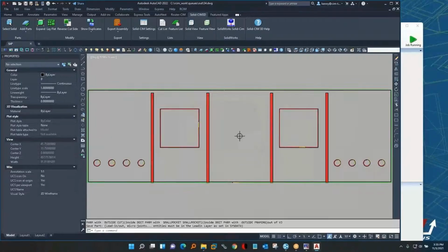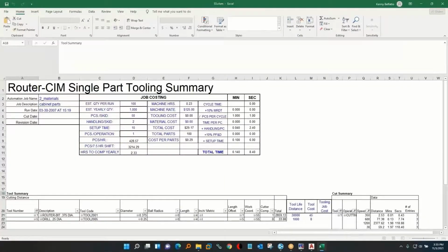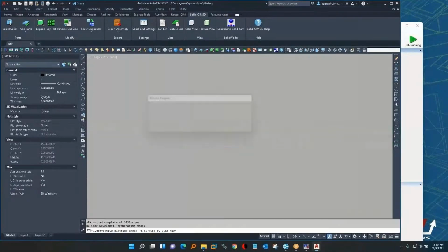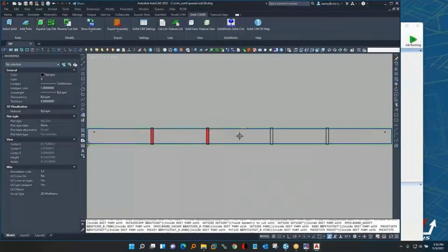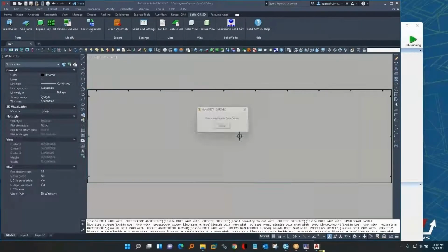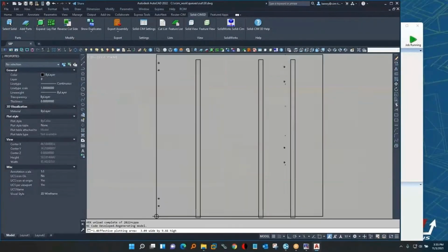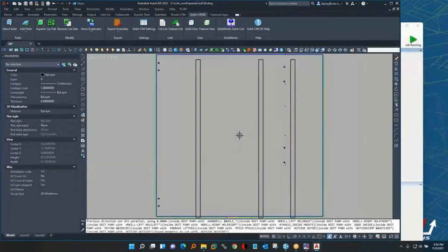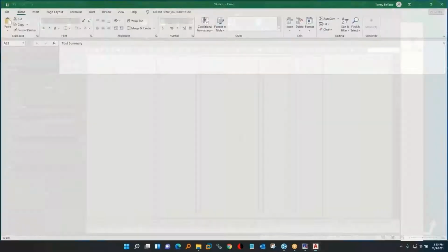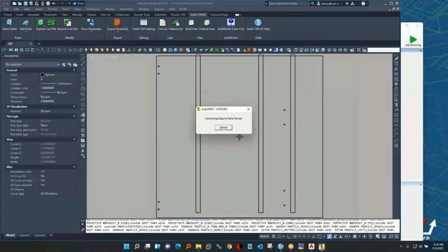Then we trim the edge of the sheet, so when you flip it over, it's a trimmed edge that goes back up against your pop-up pins, which locates it very accurately, and then it does the front side operations. So it's automated two-sided nesting, and the parts come off the table machined both front and back, right as they come off the table.